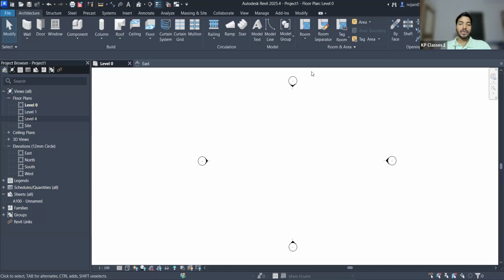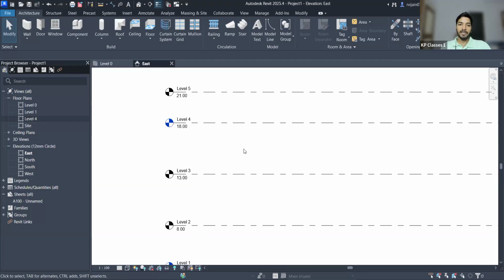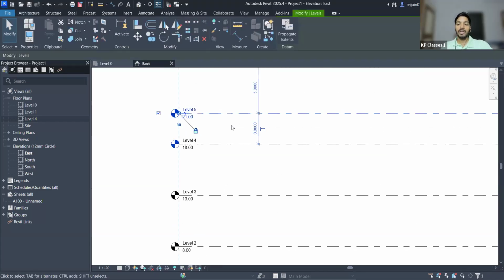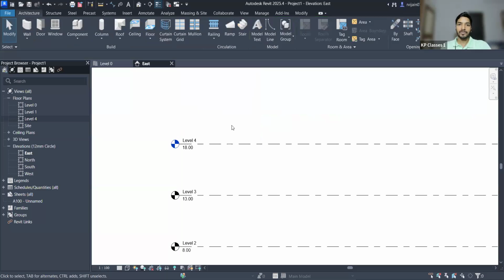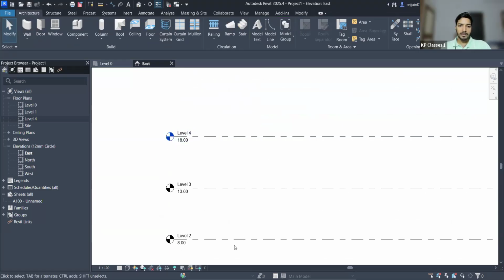So Garima, in case you want to delete the level completely, you have to go to the elevation, select that particular level and press delete. So that will delete the level entirely. Let's say this is... I'm reading through your question, Garima. So let's...